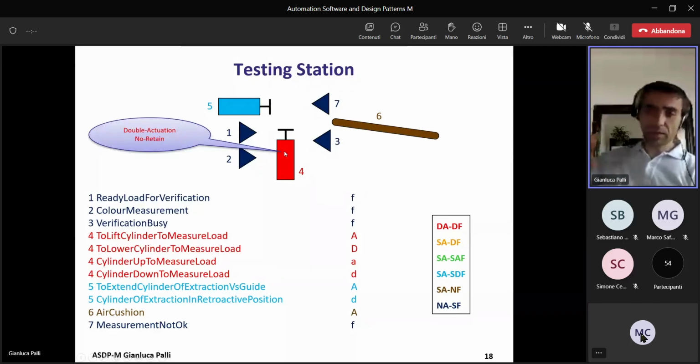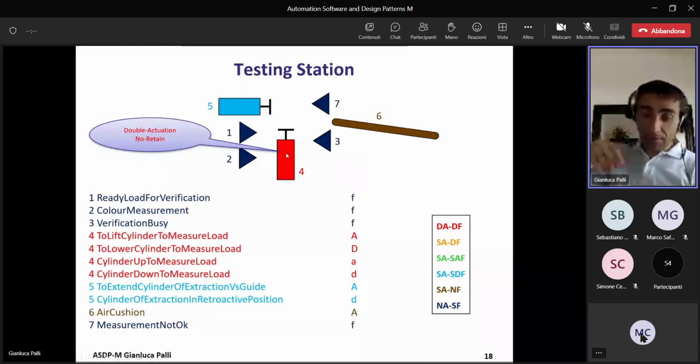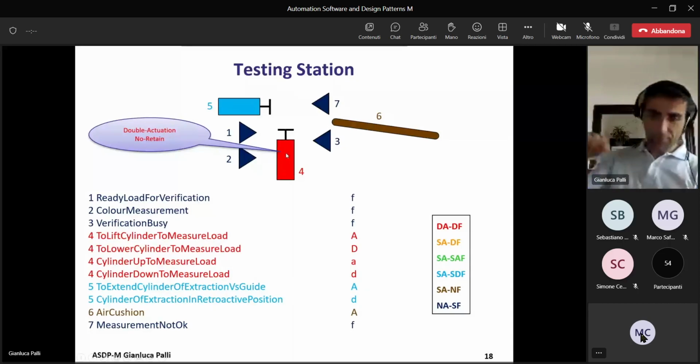It is a magnetic system that is disengaged, and this basically makes the elevator not work, or even worse, if this mechanism is disengaged, the platform falls down and hits the ground in a quite hard way, generating a very loud noise. So this can be recognized as something faulty very clearly. It's not dangerous for the system, but of course you have to prevent it, because if this happens, you have to recover the actuation by a specific maneuver.